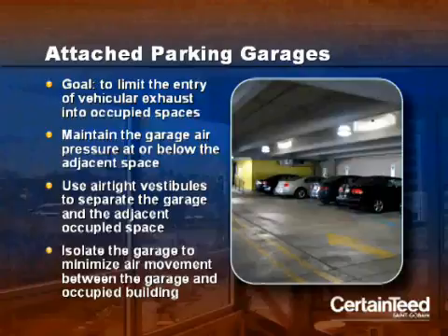Vehicles are entering and leaving frequently, and sometimes running for extended periods of time. The standard recommends that air pressure in the garage be maintained at or below the pressure in adjacent space, so there's no pressure differential that draws exhaust gases into the building. Airtight vestibules should be used to separate the garage from the adjacent occupied space. Good design should isolate the garage to minimize any air exchange between it and the rest of the building.